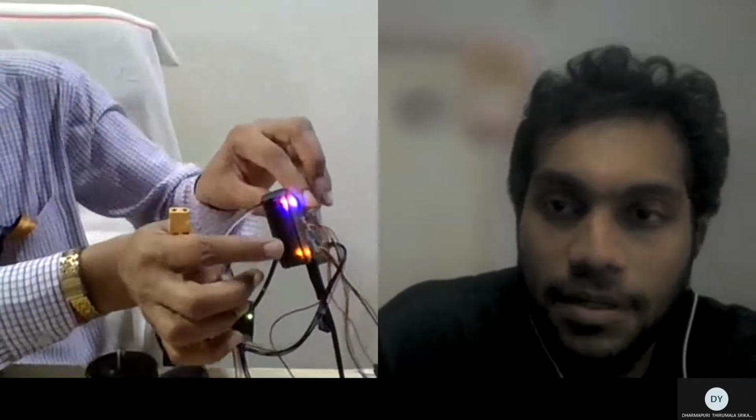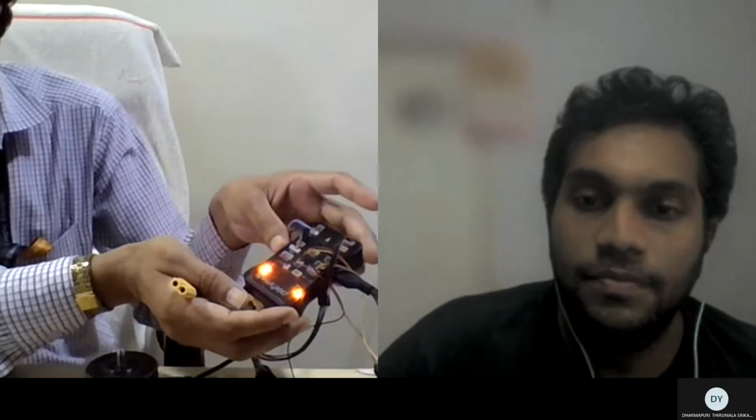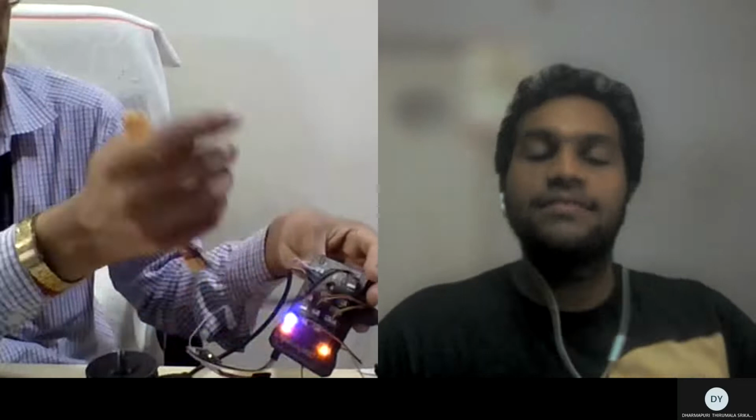Now what is the next? So that means the flight controller is always powered, right? Yes, that will be powered through the power module. That will power the whole system, not your rail. Getting it, right? And sir, your signal will come from here only. If your signal is not coming from here, then what is the use of this autopilot system? Maybe every function is working, the powering is correct, all sensors are working. I will show you through the GCS side, and only the output side is not coming.